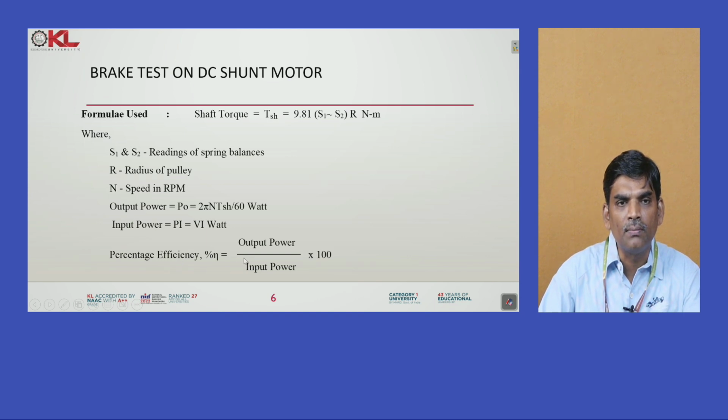It is a simple experiment. Generally this experiment is used for motors below 5 HP. Why? Because for big machines, indirect methods are normally used, which is another method. But here in the brake test, this is the way to calculate it.